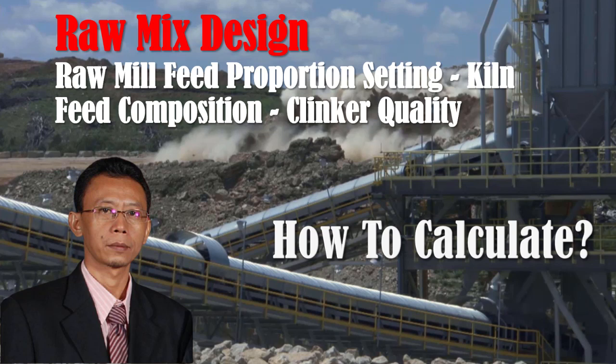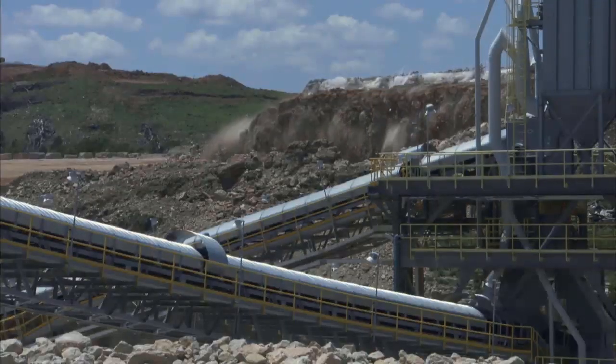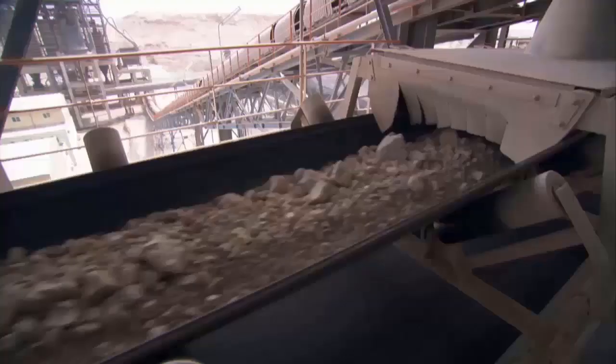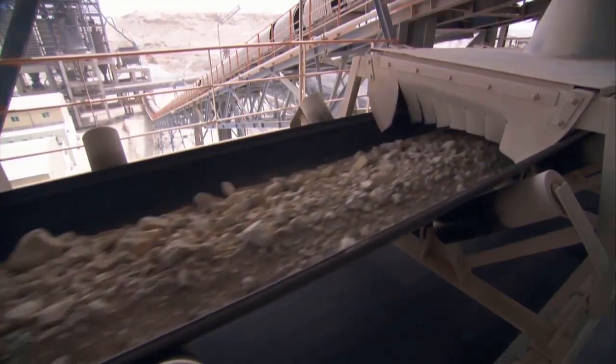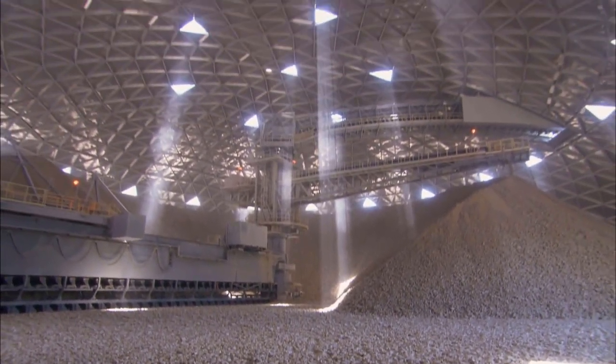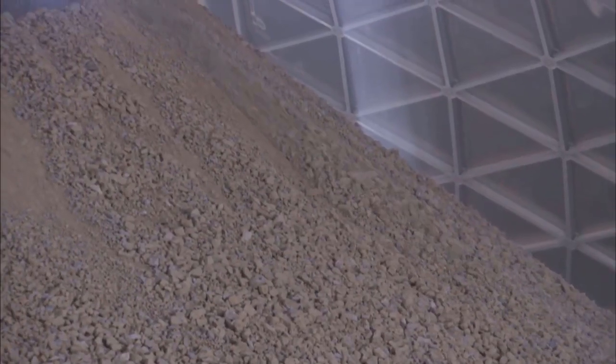Raw mix design for raw mill and kiln cement operation. The first goal in preparing raw materials is a thorough understanding of the raw materials available for the needs of the cement plant. Most cement plants are built at or near their calcium oxide source, as limestone represents about 2/3 of the mass of clinker.